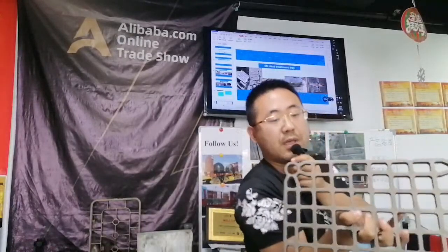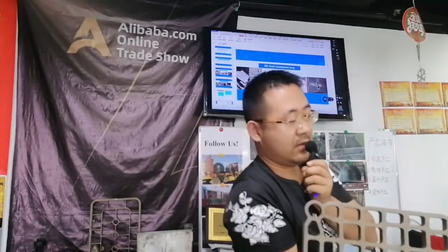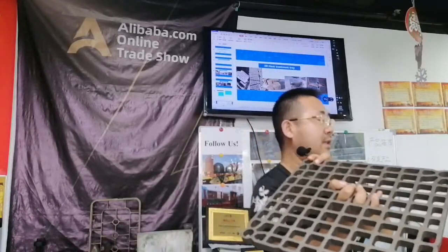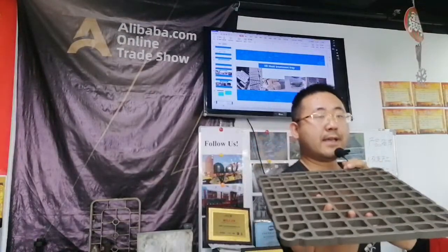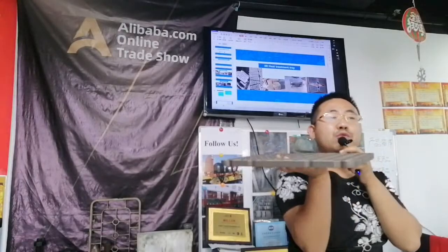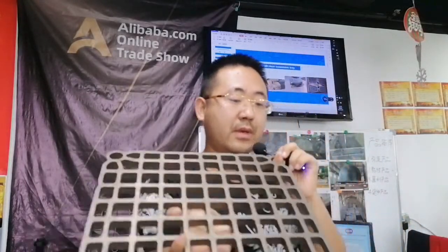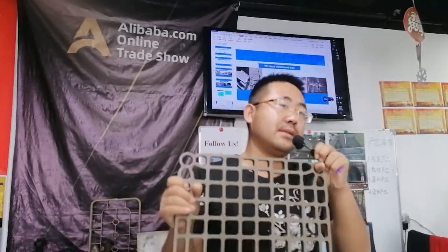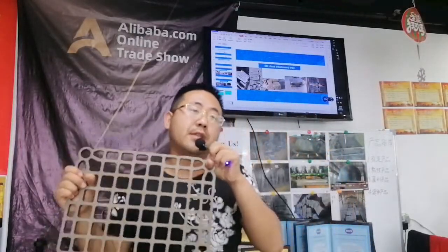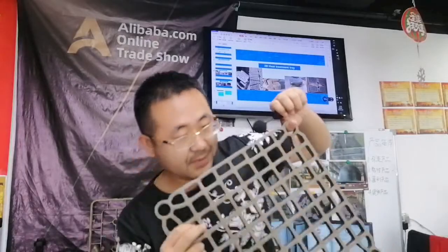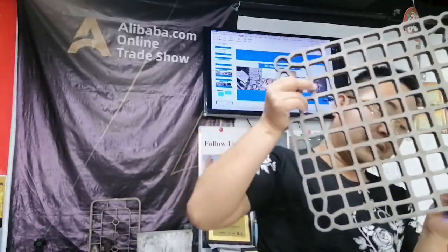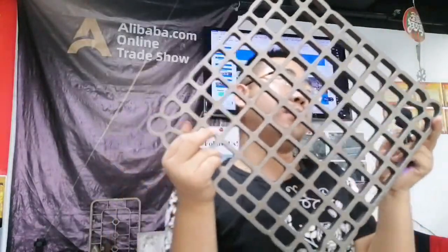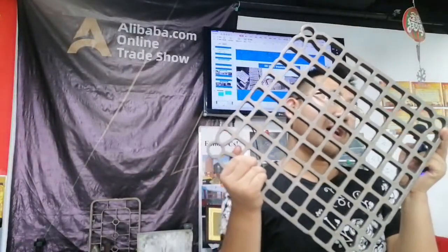This side is about 300, and the long side is also 300, and the height is about 20 millimeters. And we make marks on this tray, including the heat number and the material numbers, like this. This material is 1.4865.